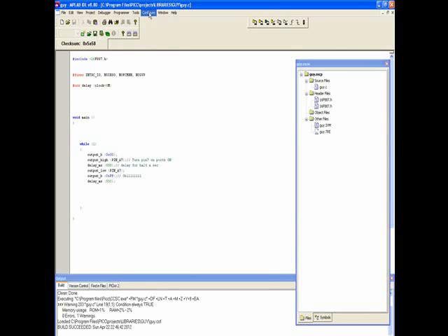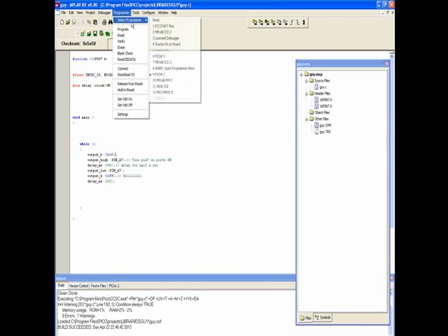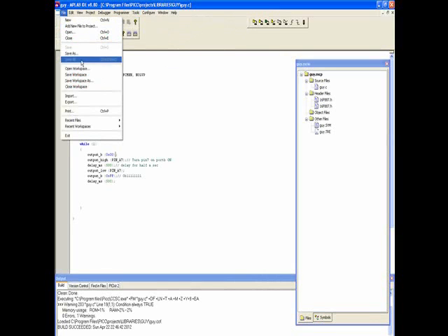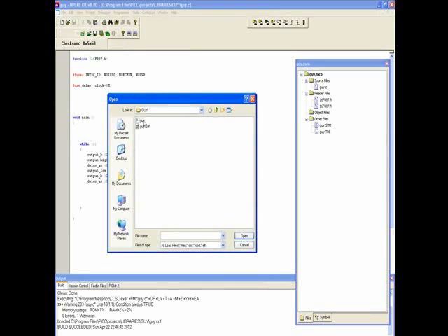microcontroller? What we have to do is go to configure, we go to programmer. In my case, I'm going to use PICkit 2, so let's go to PICkit 2. We select PICkit 2. Okay, now I'll show you what I'm doing. I've selected the programmer PICkit 2. The file that we've just compiled is a hexadecimal file now, so we have to import it. So import. Okay, now you see it's generated here.